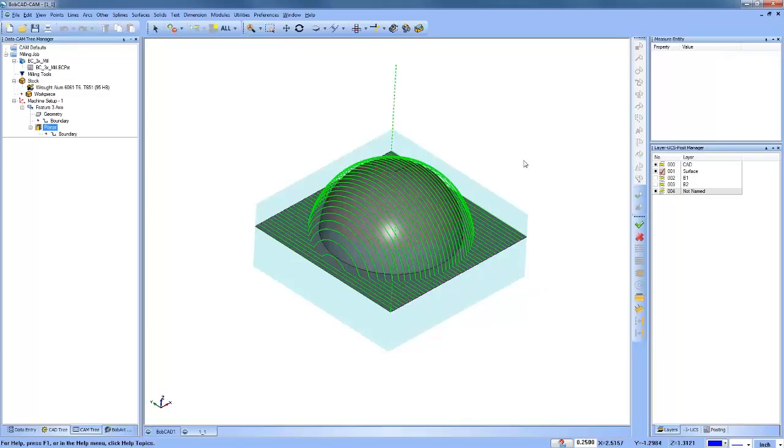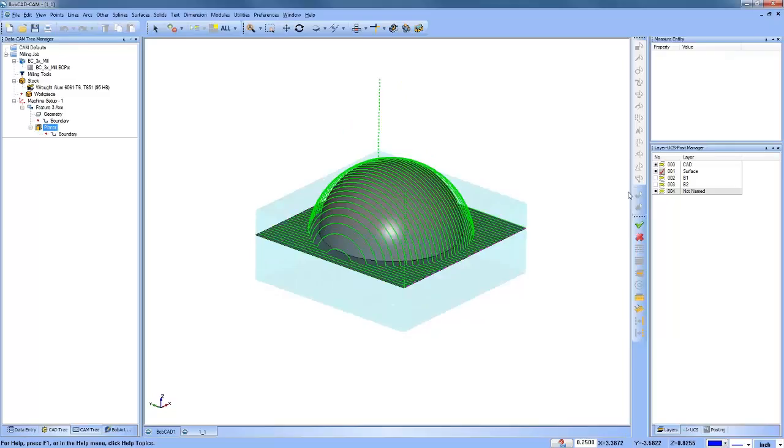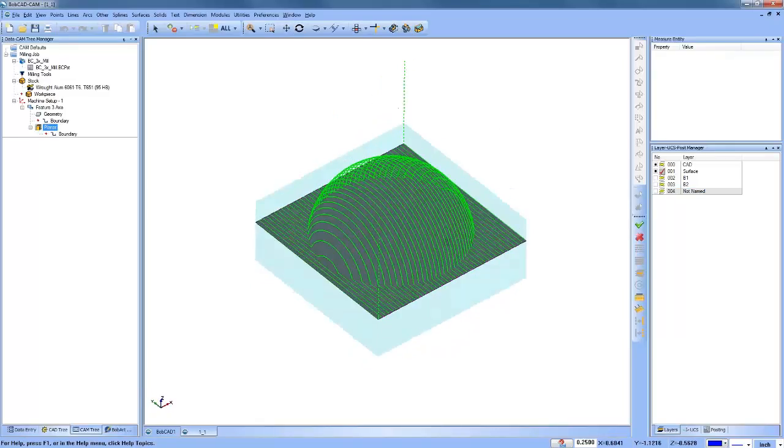All right, so I just have another example here. I had toolpath along the flat. Now what I want to do is look at making some edits along a more curved shape. This one we have going up in Z. The reason I'm bringing this up is your boundaries are generally used to contain X and Y, and what's kind of cool about the trim and relink is now you can get into different areas.